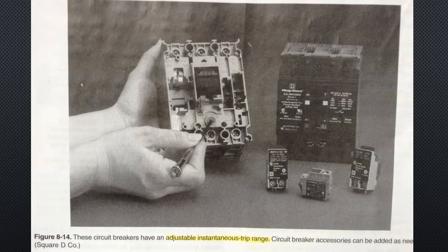Circuit breakers. Circuit breakers are permitted to serve not only as overcurrent protection devices, but also as a disconnecting switch. They are often operated mechanically. They are often operated electrically or pneumatically, but must also be capable of manual operation. Circuit breakers must be marked to show if they are on or off. This indicates if the circuit is closed or open, respectively.